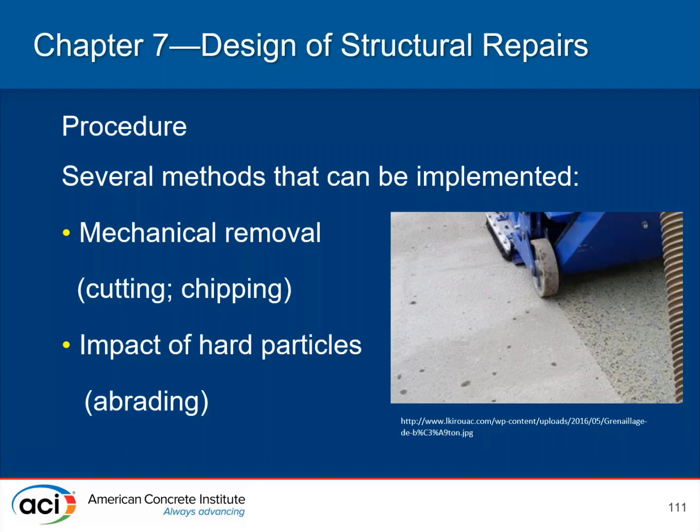Shot blasting and sandblasting both act to, although they don't create as large of a surface profile as chipping, help remove bruised and microfractured concrete that can be a result of chipping. This helps remove all the distressed concrete at the very near surface area for creating, again, a sound bonding surface.